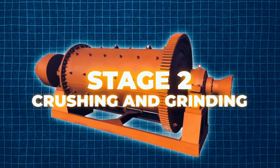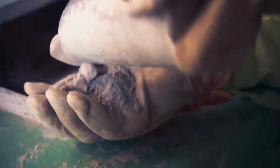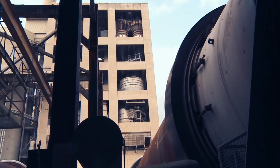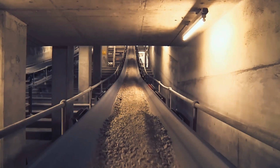Stage 2. Crushing and grinding. The first step is to break the raw material so that the rocks are smaller. Hard rocks are broken up by jaw crushers, hammer mills, and cone crushers in cement plants. The hard rock is then turned into a fine powder called raw meal by a process called roller milling.